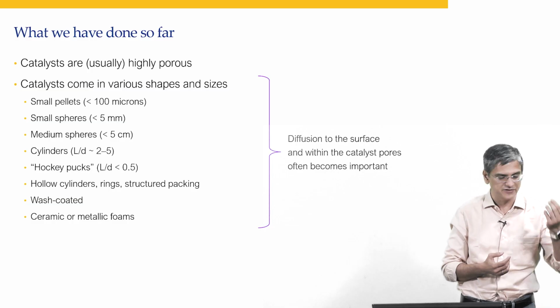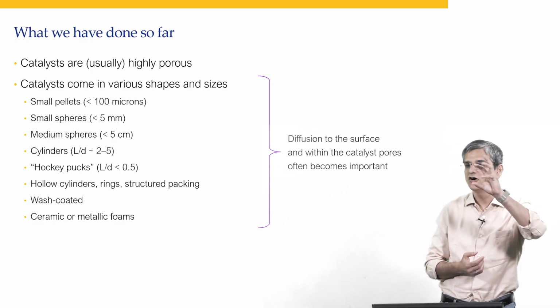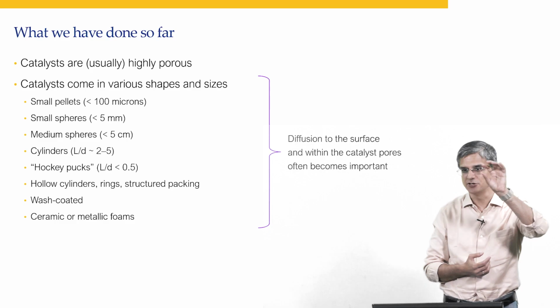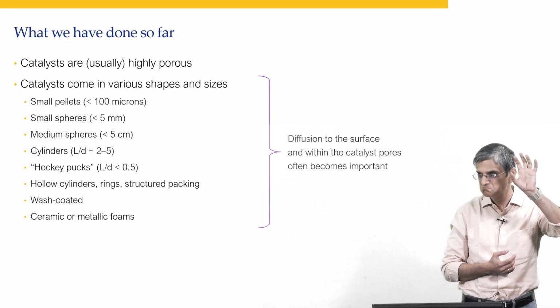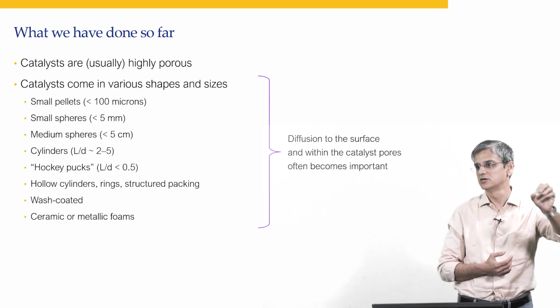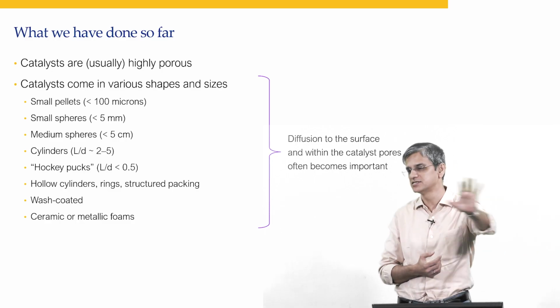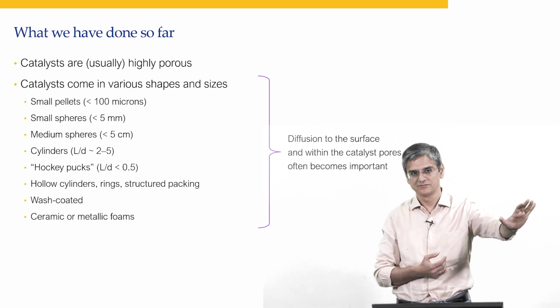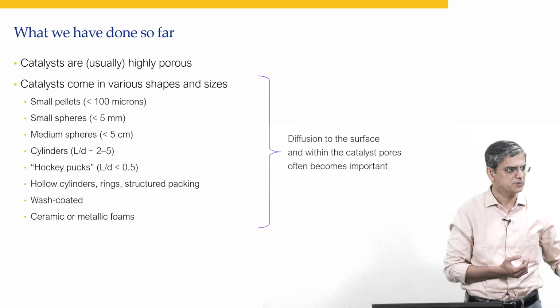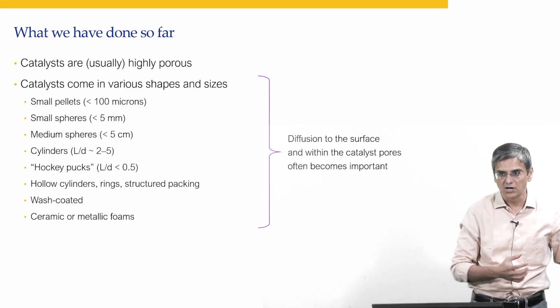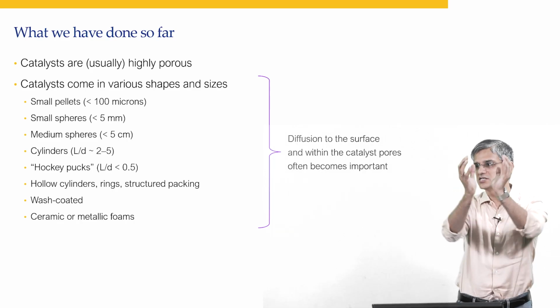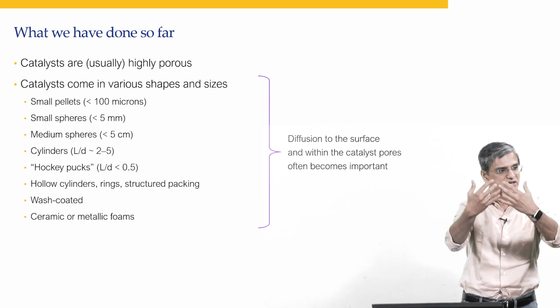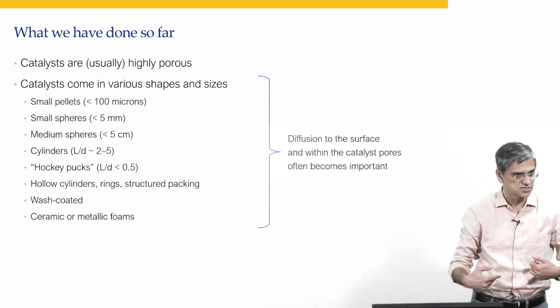It's either a very fine powder or very porous granules. Exact same concept. Only mass transfer is relevant over there. Here it is mass transfer plus reaction. But if you have a larger sized particle, you want it to be very porous, so diffusivity is higher.